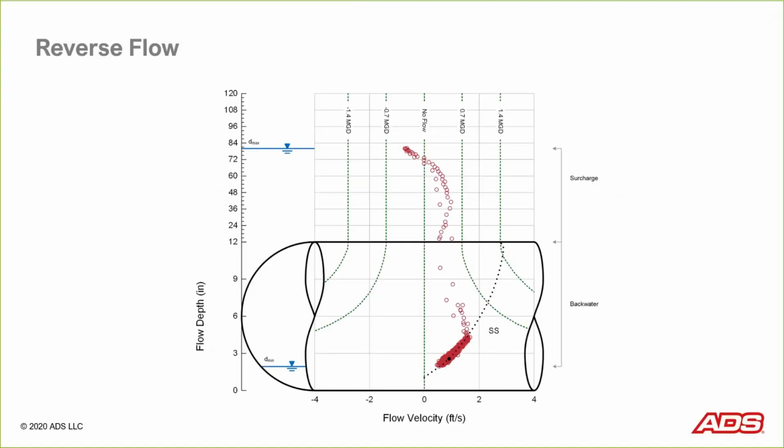So this sewer, day in and day out, below, say, half pipe, is operating pretty much as we would expect it to. It gets a little more full and it goes into backwater conditions. So this is perhaps during a rain event. It surcharges, and you'll notice that as it continues to rise in depth, in a surcharge condition, the velocity starts to get slower.